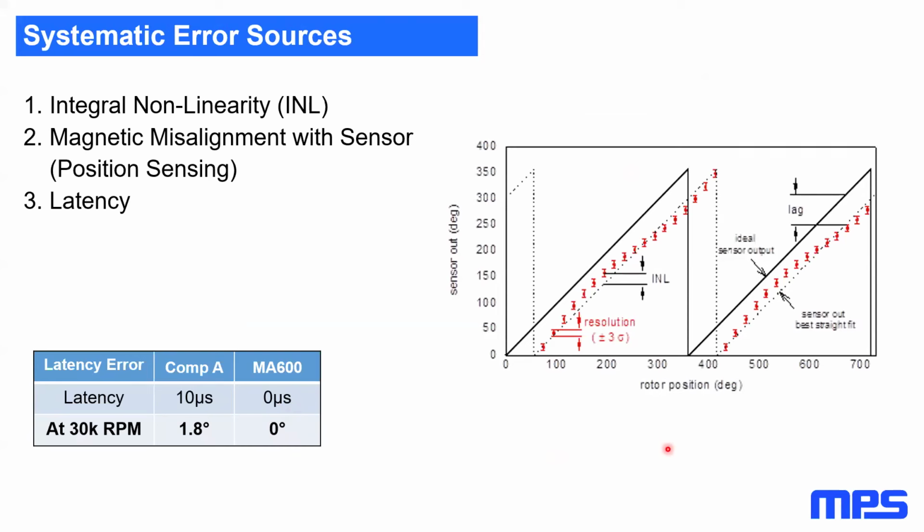So I would compare it to a Kalman filter. It's not a true Kalman filter, but you can compare it to that. It essentially uses the velocity state variable to estimate the speed and then corrects the position based on the speed and the known latency, if that makes sense.